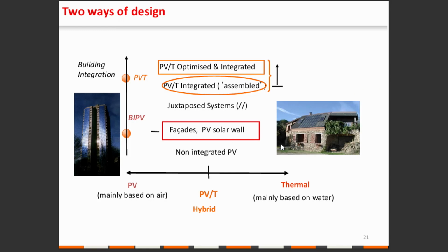I showed already two ways. The more active way is to master the fluid circulation, a calorific fluid that could be water, oil, or air, or a passive way, where you just try to find solutions that passively will allow to decrease the temperature of the components. And the best is natural ventilation, to try to find a siphon phenomenon to get natural circulation.